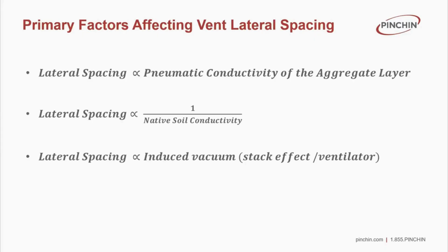And then lateral spacing is directly proportional to the induced vacuum. So through the vent riser, whether we're using stack effect or we are using a ventilator turbine, we are essentially inducing a vacuum to the subslab environment. And the higher the vacuum we are inducing, or we are able to induce, the farther away we can space out these laterals.